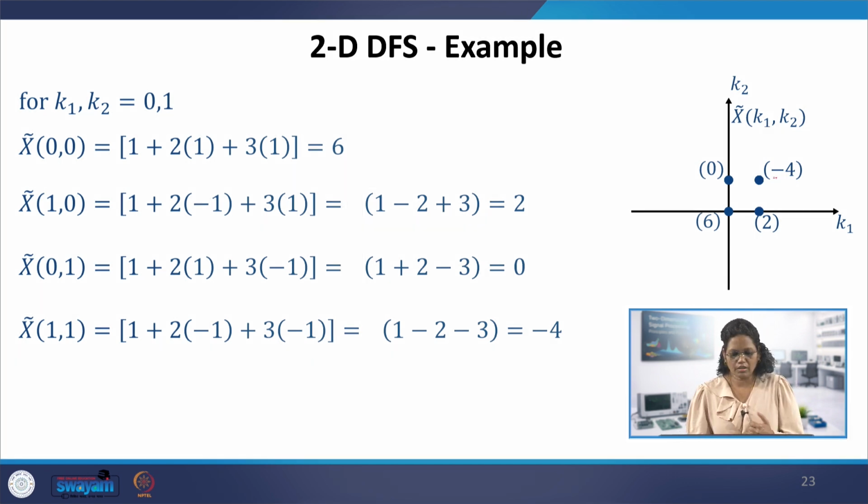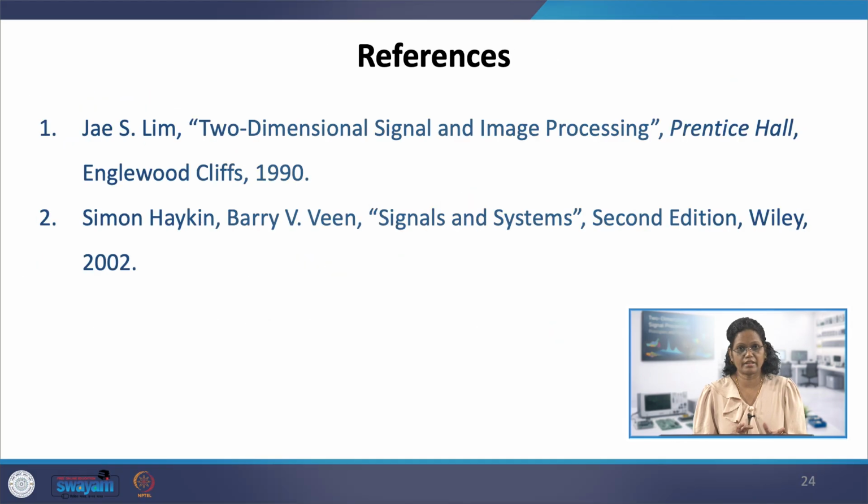With this we have seen the properties of the discrete Fourier series, which we call DFS, as opposed to DTFS in 1D, because the time parameter is dropped in the 2D case. The 2D DTFT is called DSFT, whereas this DTFS is called DFS. We have seen the important properties, and how to do the circular or periodic convolution, which is simply the multiplication of the 2D DFS of the two sequences.